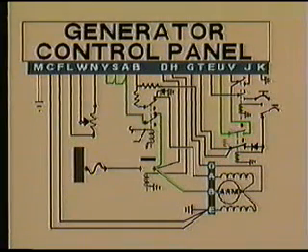Two sets of contacts within the relay play a dual role. The main function is to provide a path of residual and subsequent increasing voltage from the generator B terminal through the output control relay, into the control panel, back out through the reset relay, then back into the panel. This seemingly long, drawn-out loop serves two important functions.